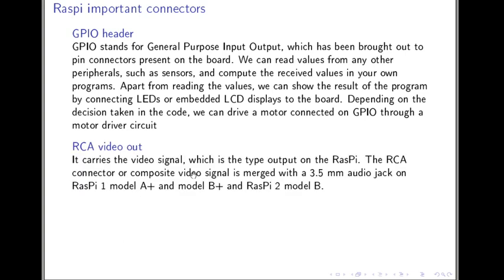Mainly the Raspberry Pi is used as a computing device, which means it acts as a gateway device, and the microcontroller is an end node device connecting directly to the sensors. So remember, Raspberry Pi is for a gateway or edge device. If you have to carry out some computation at the edge level, we will use Raspberry Pi, because its processing, as we have seen, is much more.